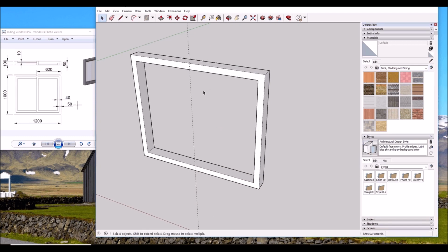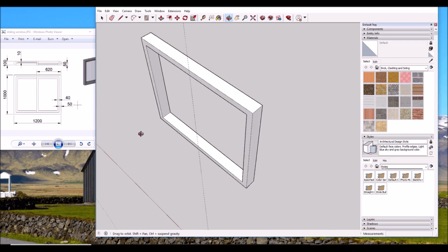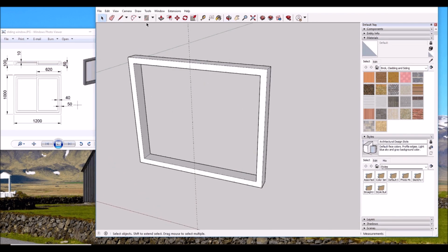You see it will draw a construction line from that face. Now I can draw a rectangle from the intersection here to the intersection here. See, I don't need to press arrow because I picked two opposite corner points. SketchUp knows this is the rectangle you want.